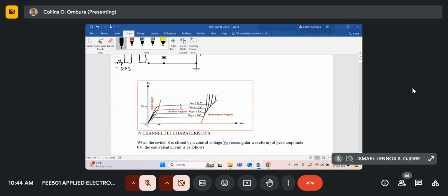So you see when the VGS is equal to 0, it's conducting maximum. As you start putting a negative voltage of VGS, the current lowers. And of course, an FET has got a maximum voltage you can put across it before it breaks down. So in this region, it's breaking down. In this region here, between 0 and VP, this is called the pre-pinch-off region.